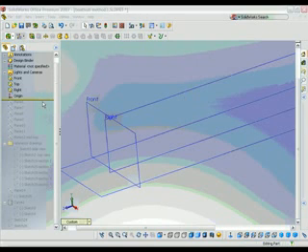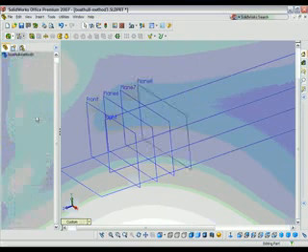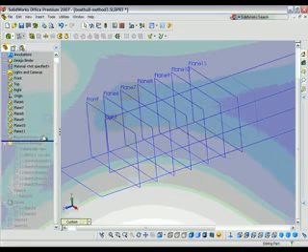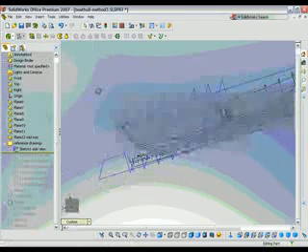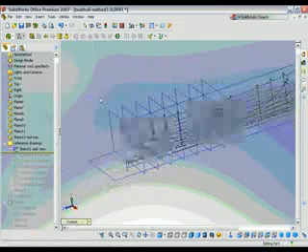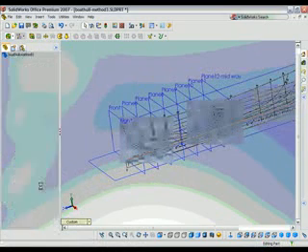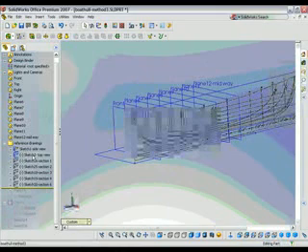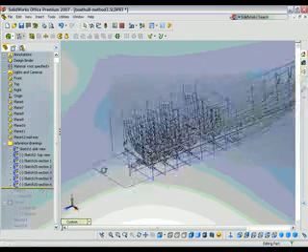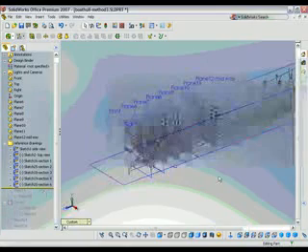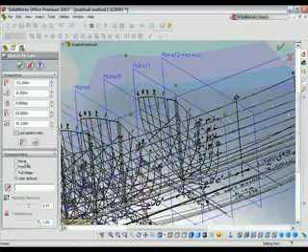So here's how I created this. I created a number of reference planes using reference plane offset with the copy option feature, and placed my first side view of the boat in that right plane. And then in each of the offset planes I created a sketch picture and placed that sketch picture identical in each of those planes. Let's show you one of them.